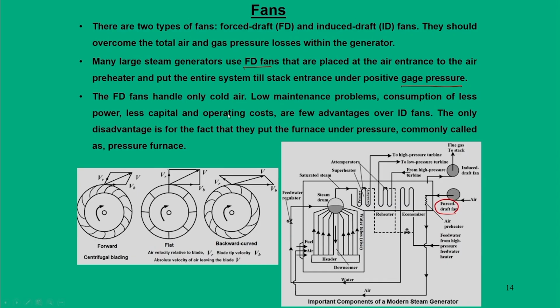And these forced draft fans handle only cold air from the atmosphere. Because of this they have advantages like low maintenance problems, less power consumption, and less capital and operating cost. The only difference is that since it is always pushing the air into the system, the unit is already under pressure, and we call this a pressure furnace.